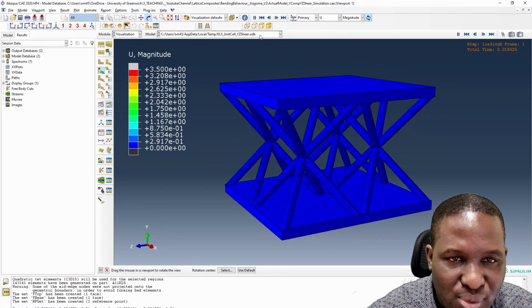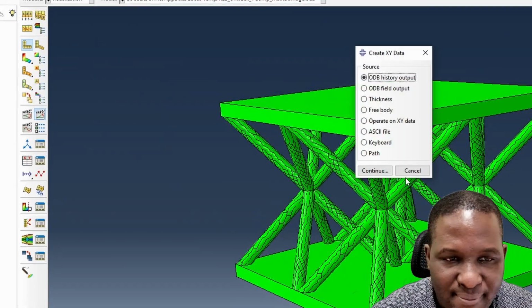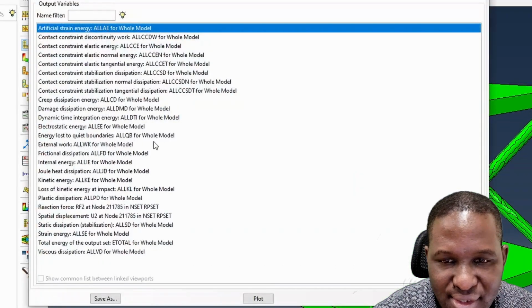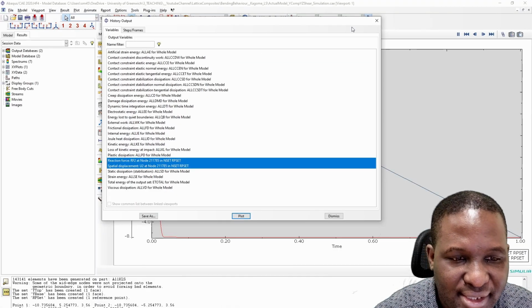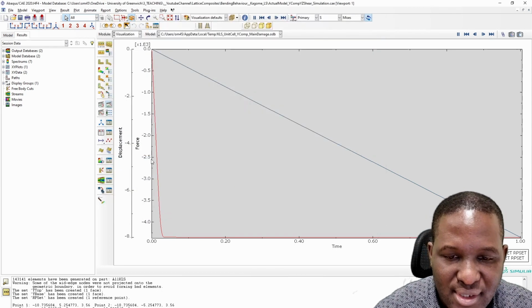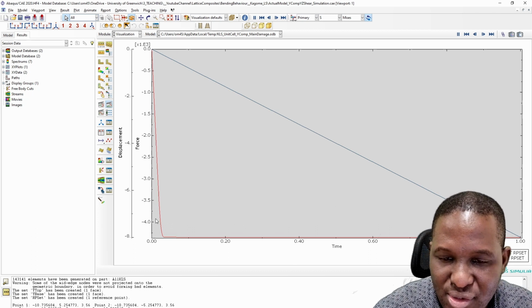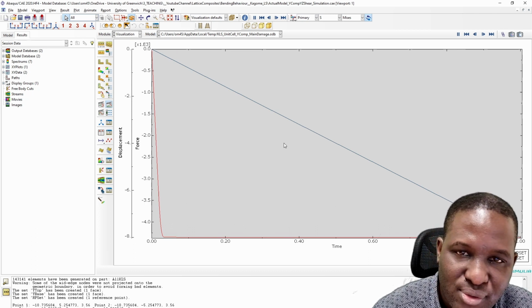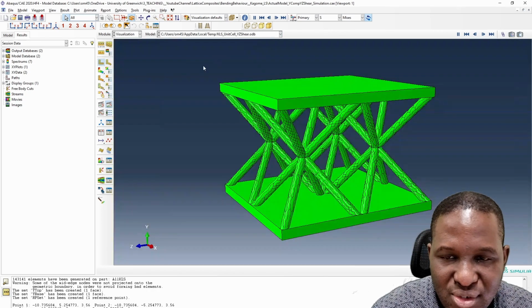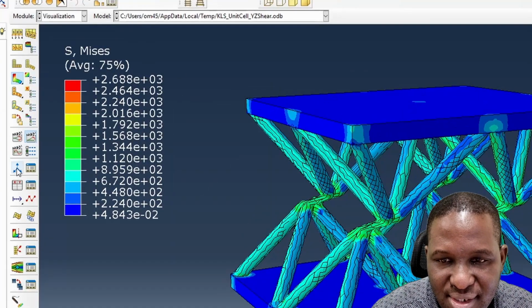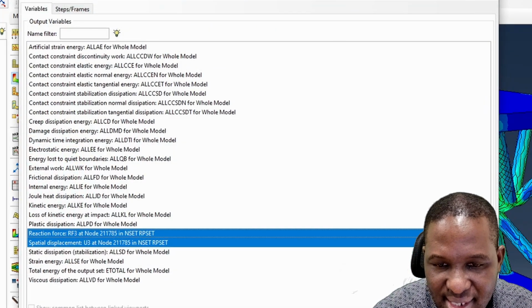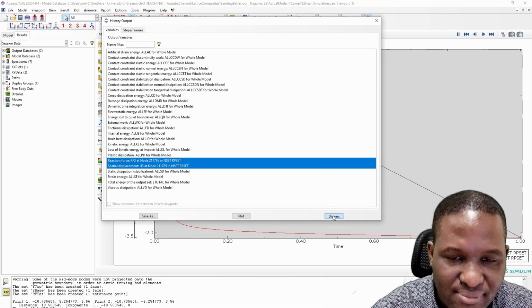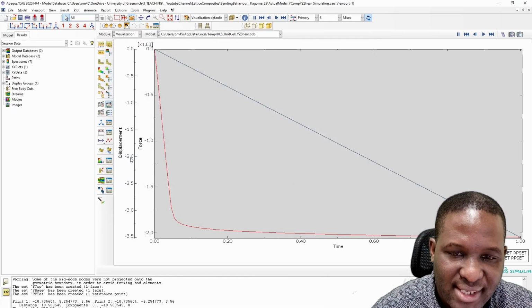So the final thing we can do, if we go back to the Y compression, is look at the data. So we clearly are interested in the Y-axis behavior. So you plot that data, and then it shows you what's really happening. So there's a kind of elastoplastic behavior on the structure. So once plasticity is reached, you get this plastic deformation in the structure. So if we move this around to the shear strain data, we could see what's happening with the shear strain. Again, the shear strain will be the y-axis, the third axis result. So again, you get some interesting results of the profile elastoplastic behavior.